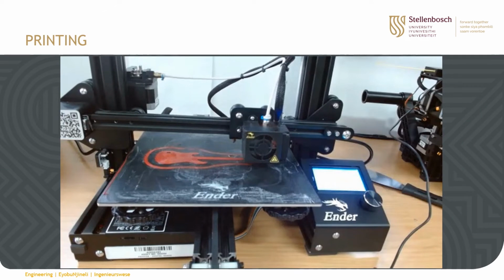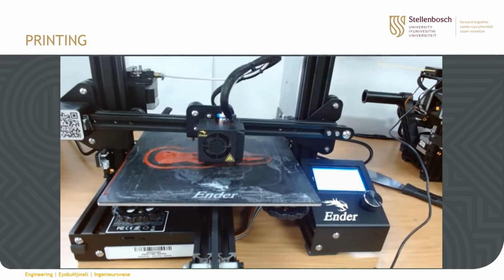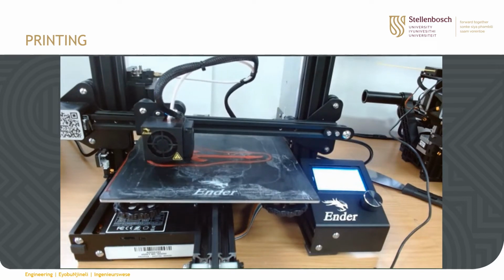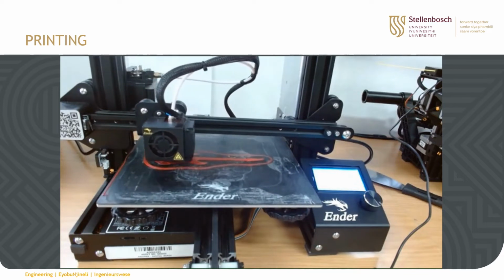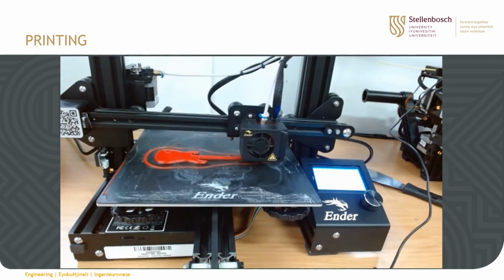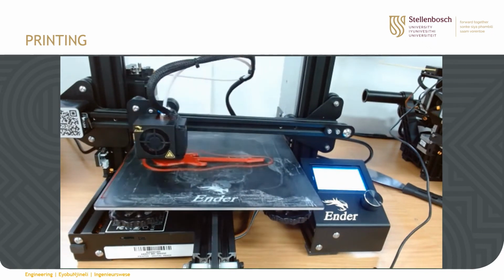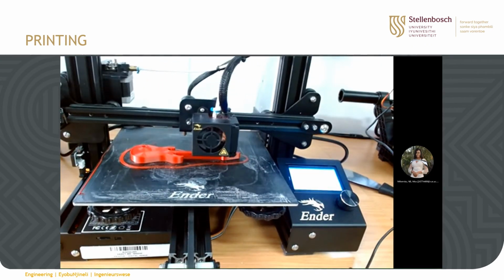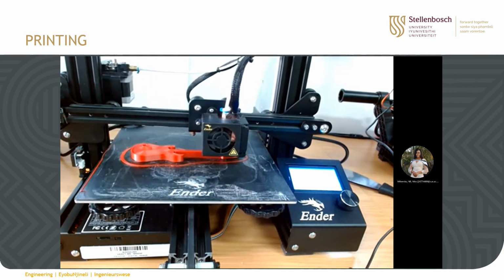And now for the printing part. You are probably wondering why this guitar is surrounded by this weird looking shape. This is not for decoration. This is essential for dimensional accuracy. So to make sure that the bed is leveled properly and that the part you're printing sticks on the build platform without any distortions that are influenced by uneven cooling, a few test layers are printed before the actual part so that adjustments are made if they are needed. And there you have it, doing the final layers, and then you have your part.